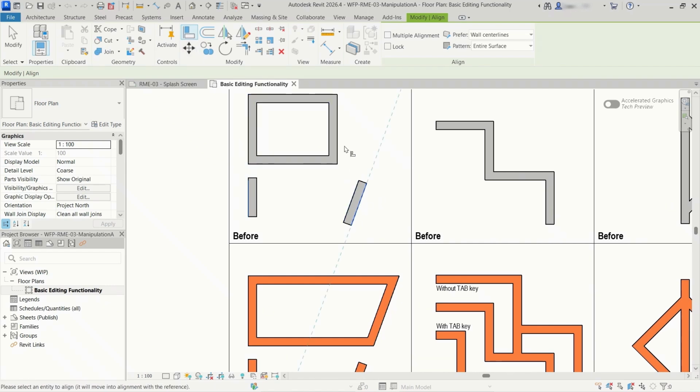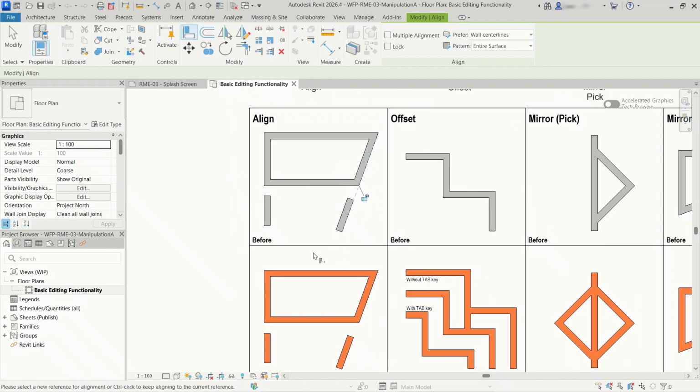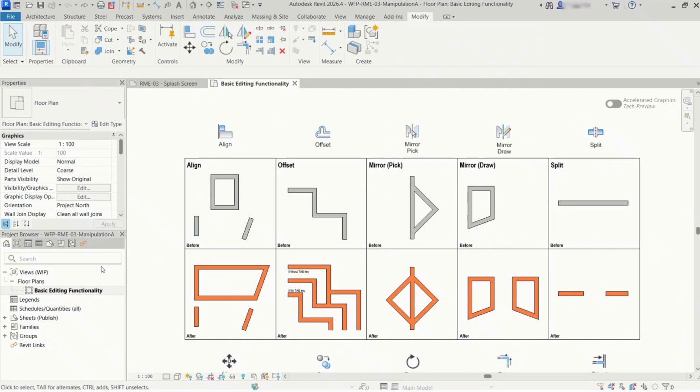Keynotes: tool must be selected before clicking components. Clicks must be precise. Revit aligns based on the face or edge clicked. Can align to lines, reference planes, grids, levels, or straight edges. In some cases, alignment may cause rotation while maintaining wall connections.